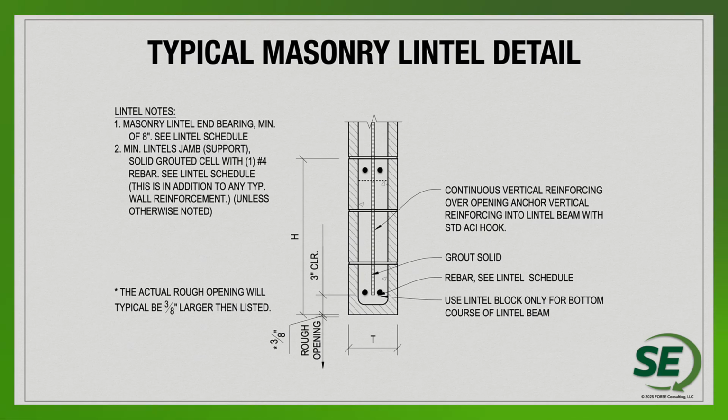Also considering what some of the different covers would be, different types of blocks really would have to be considered. The different geometries of those blocks, where can the reinforcement actually be placed in these different types of blocks, what are some of the different clear distances that are required by code, but then what are some of the clear distances that are going to result just because of the different types of lintel blocks that are being produced today.